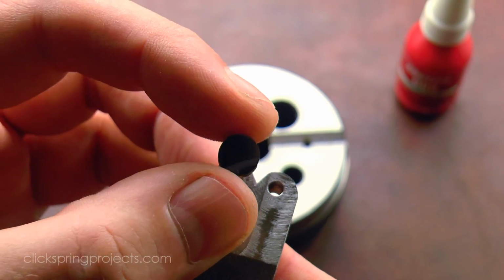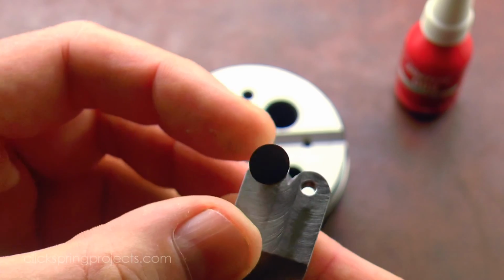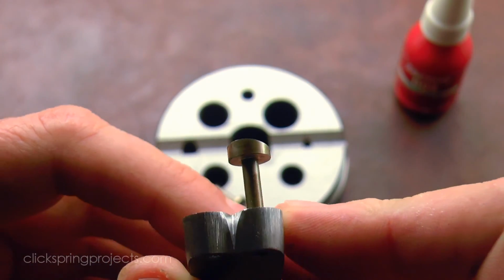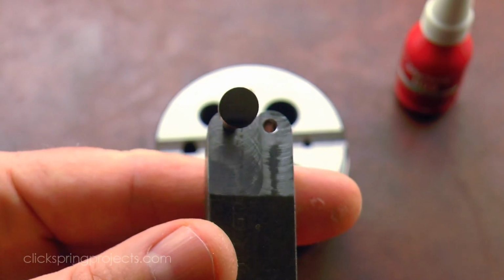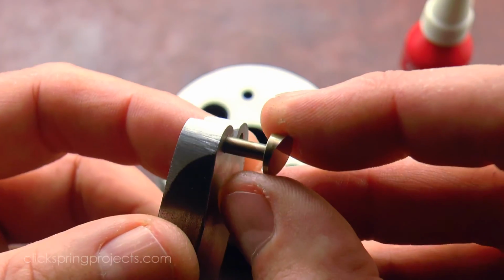The button cutters are then manually positioned on the shank, ensuring a 45-degree rotation of the high point of each button towards the centre line to make the most of both the rake and the clearance angles during the cut.